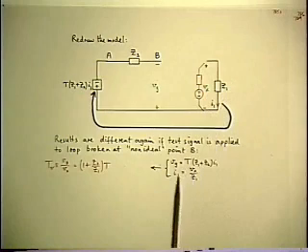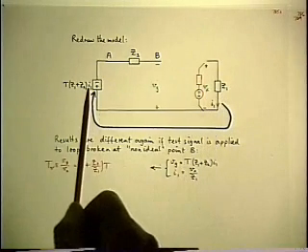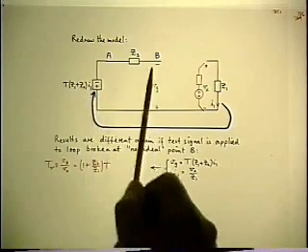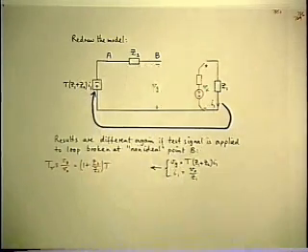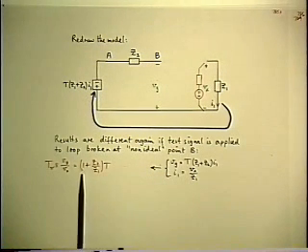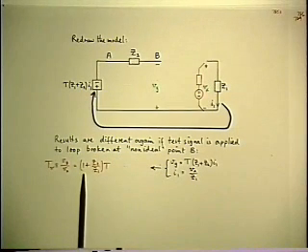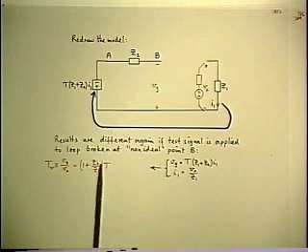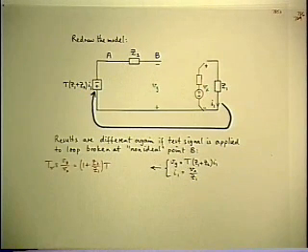Vx appears across Z1. I1 is Vx over Z1. That activates this generator. You multiply it out. And this time that generator is equal to Vy because there's no drop in Z2 because you've broken the loop. Well, unlucky again. Still not the right answer. It's a different wrong answer. But it's still not right unless that impedance ratio is low enough.